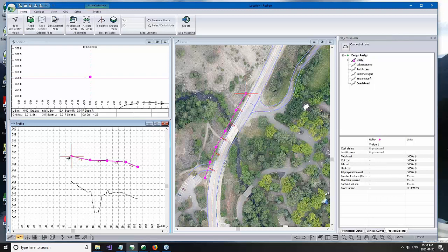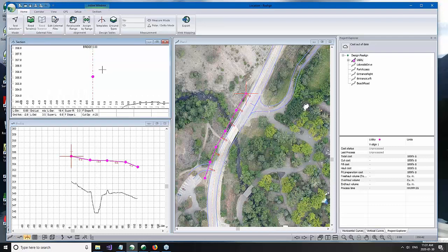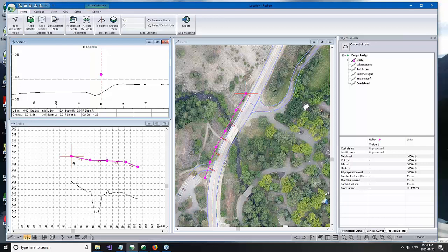Obviously, it would have to be quite a bit lower. And then once the template's tied together, I'll be honest, there's a little bit of work to set it up, but once it's tied together, you can just switch alignments, change the profile of the ditch, and the other corridor will follow along. So short answer is yes.